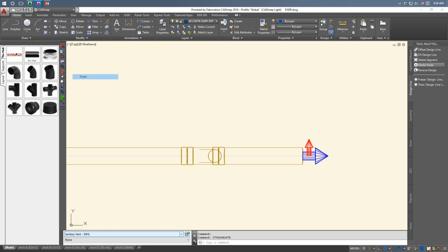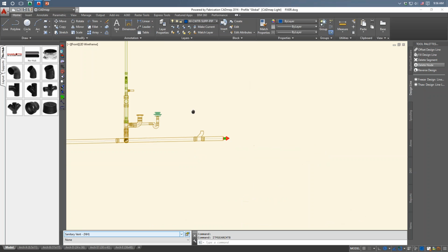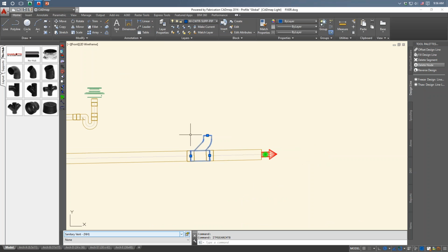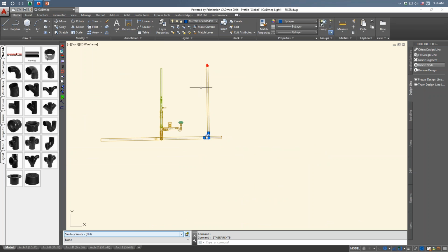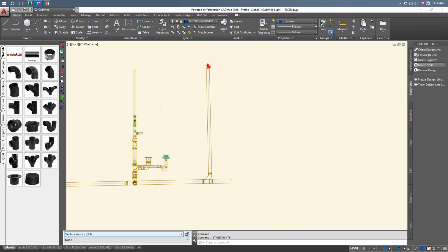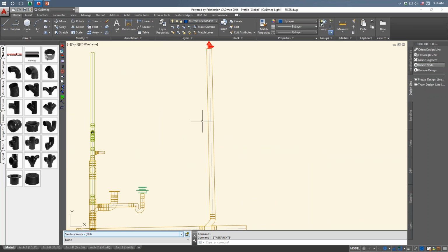So I'm going to go to a front view here. We can see that it's graded. Now if I just pull on this grip to drag a piece of pipe out, what I get is a pipe that is crooked. Well, there's a quick way to straighten that up, and that is with a tool called the positioner.